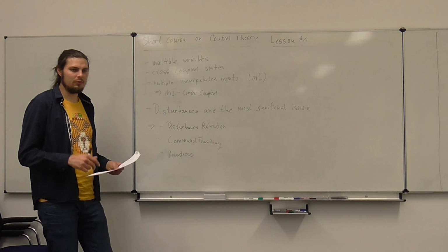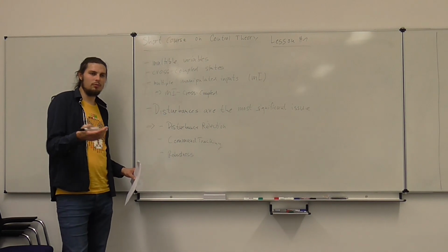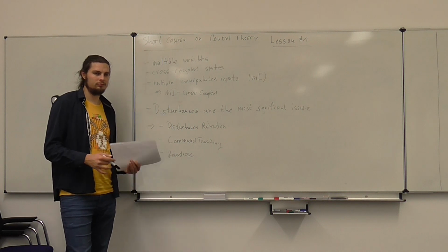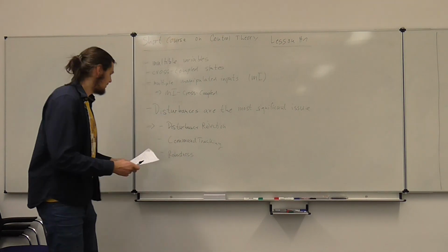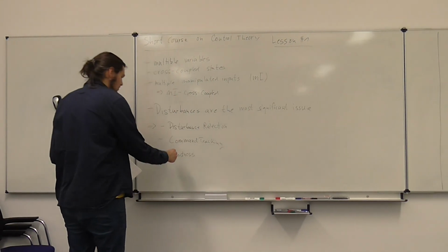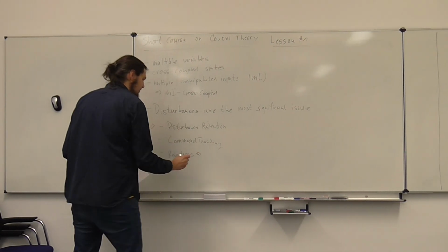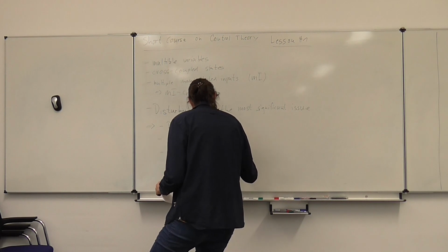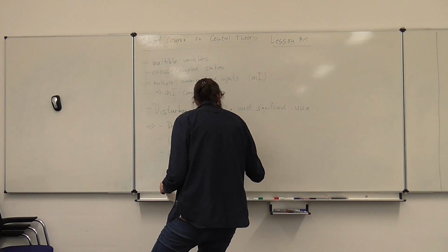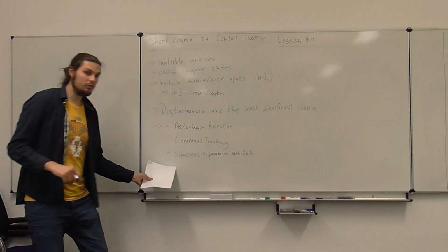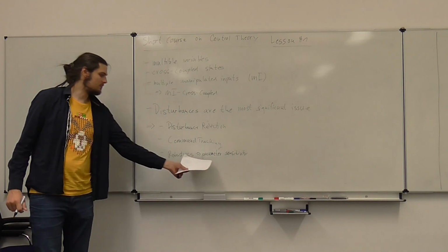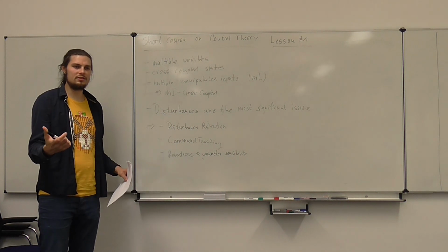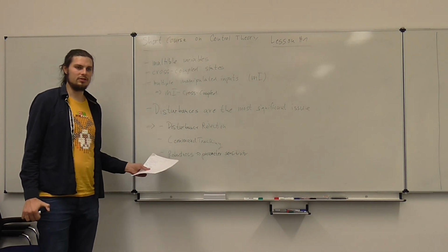And the third is robustness. What does robustness mean? What's the word robustness implying? Is it reliable? You would think it means reliability, but in control terminology, it actually means parameter sensitivity. So in control terms, when we talk about robustness, we always mean parameter sensitivity. If your control is robust, you're not very sensitive to your parameter estimation.